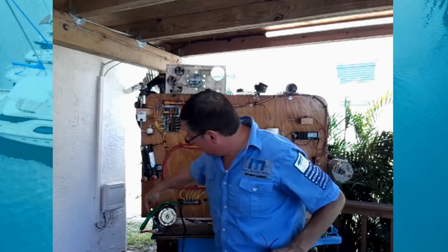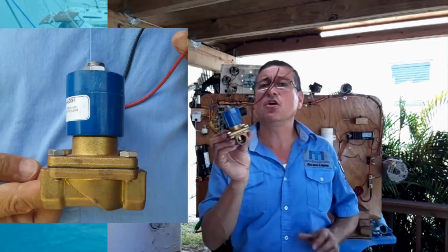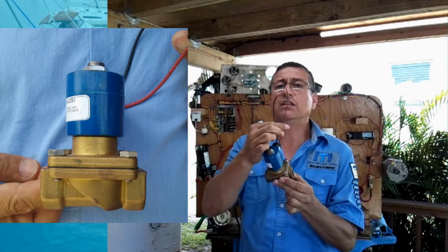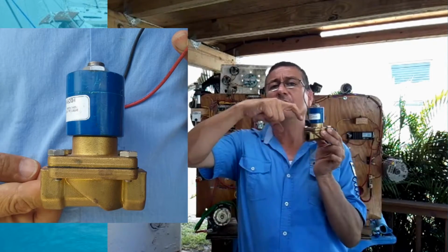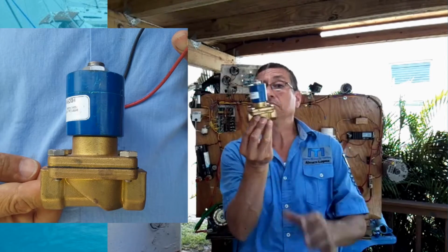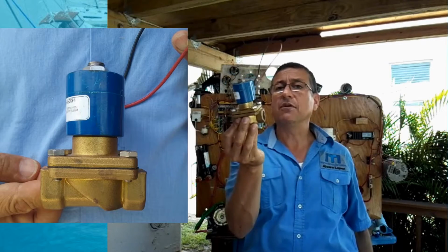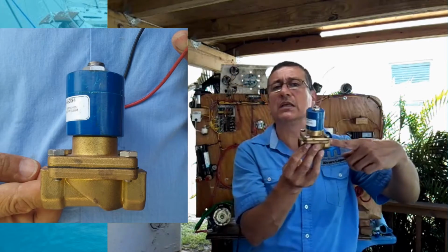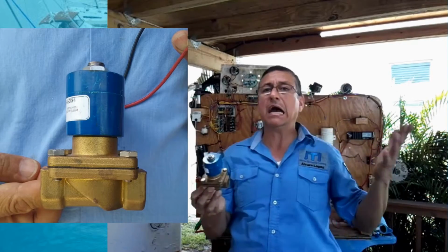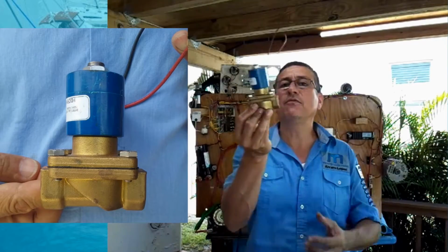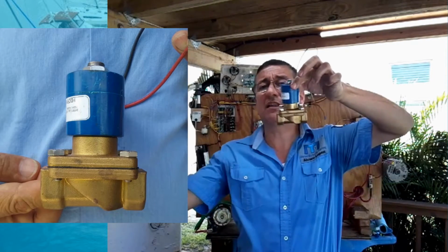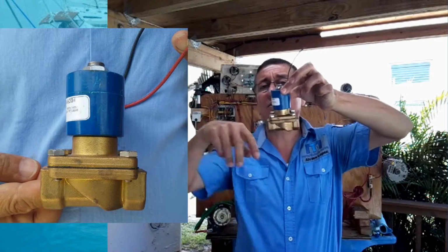The solenoids can be used in other types of applications like this. This is a solenoid. When the solenoid is powered, positive and negative, immediately the plunger closes the valve. This is a solenoid valve to control the movement of the fluid. What type of fluid? Water, gasoline, diesel, gas, alcohol, any type of fluid can be controlled. The fluid enters here and continues over there.